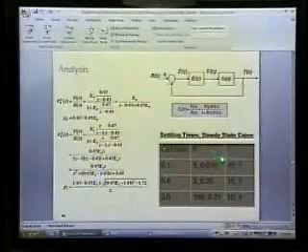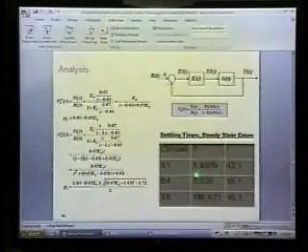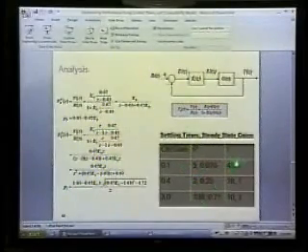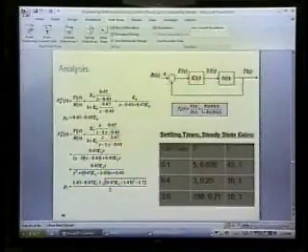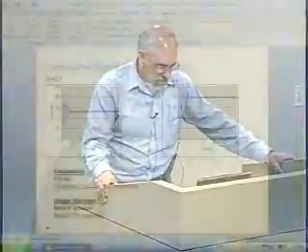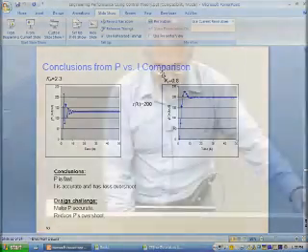We see that for the proportional controller, we come up with settling times and then steady state gains. So the settling times, there's somewhat of a drop, and then we're seeing a big increase here. Here we see a slightly more complicated behavior in part because of this quadratic, but the steady state gains are always 1 because of the nature of the integral controller. All right, so this was sort of a starting point, just to give you a feeling for what you can do with that analysis. What we're going to do now is sort of explore how we could make things better.